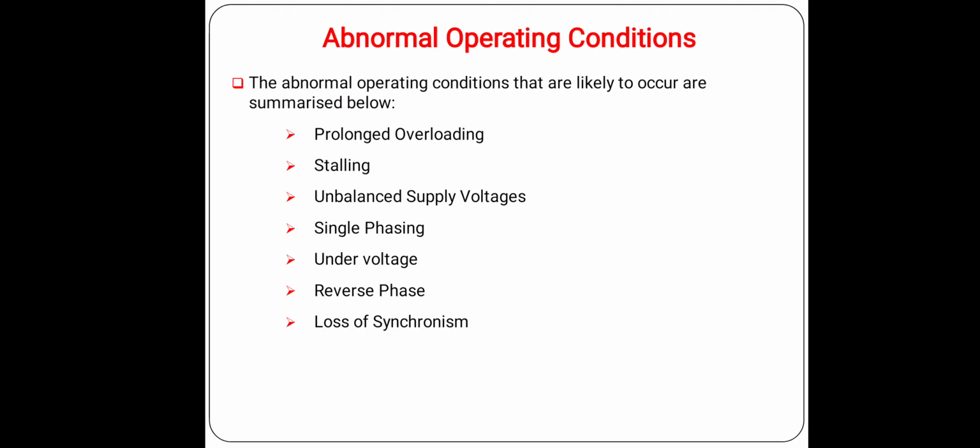Now next one is under voltage. As the name mentions, under voltage supply will generally cause the motor to draw more motor current for a given load. Hence this protection is also provided.